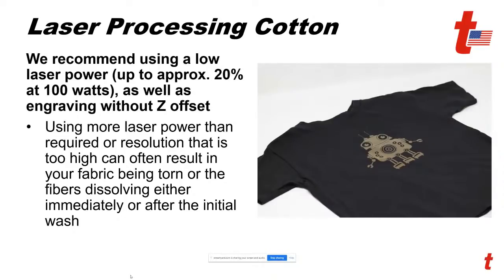Understand when you wet it down, when it engraves, it's not going to be as white as you think on the power setting. You'll have to engrave it, and then you're going to have to let it dry to truly see the finished effect. So when you're doing testing, once you've wet it down and engraved it, just because the contrast isn't good, you want to wait until that fabric has dried out. Stick it on a heat press to dry it real quick, throw it in a dryer, stick an iron on it, whatever's necessary to truly bring out that contrast and make sure your setting is right.